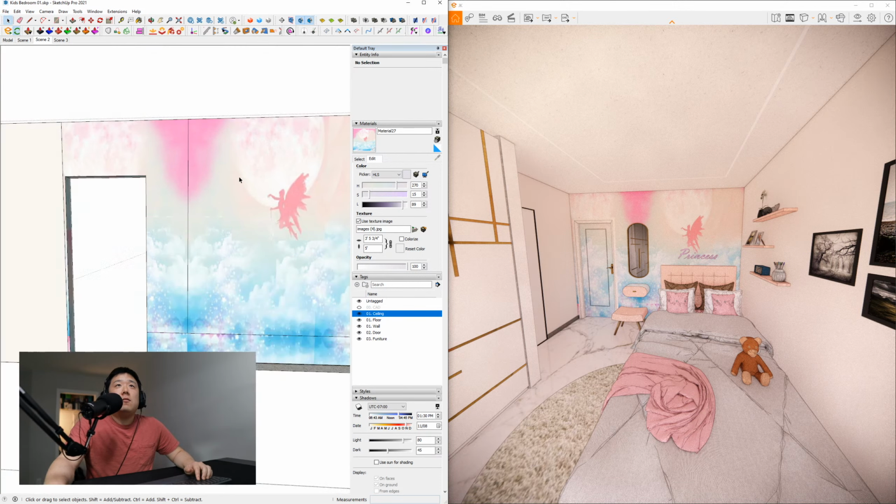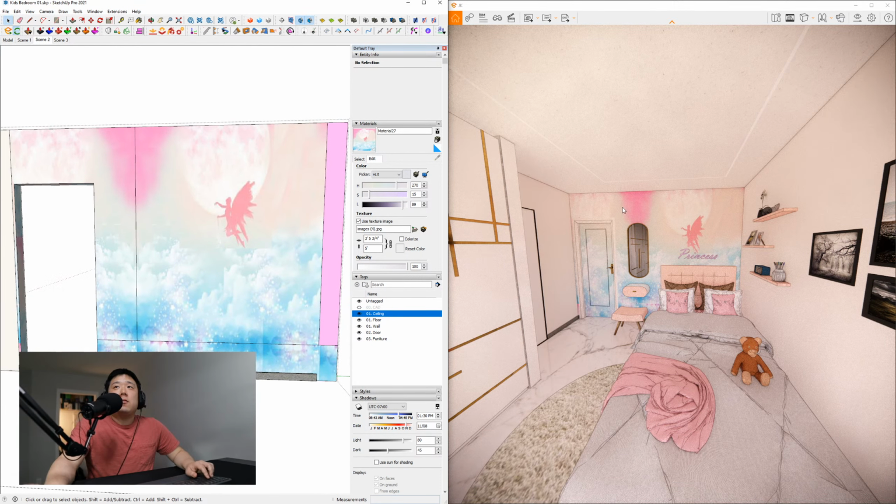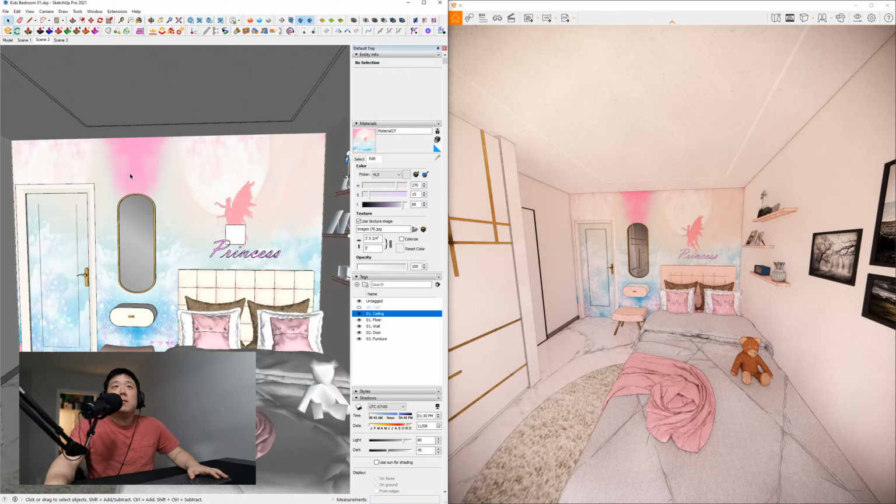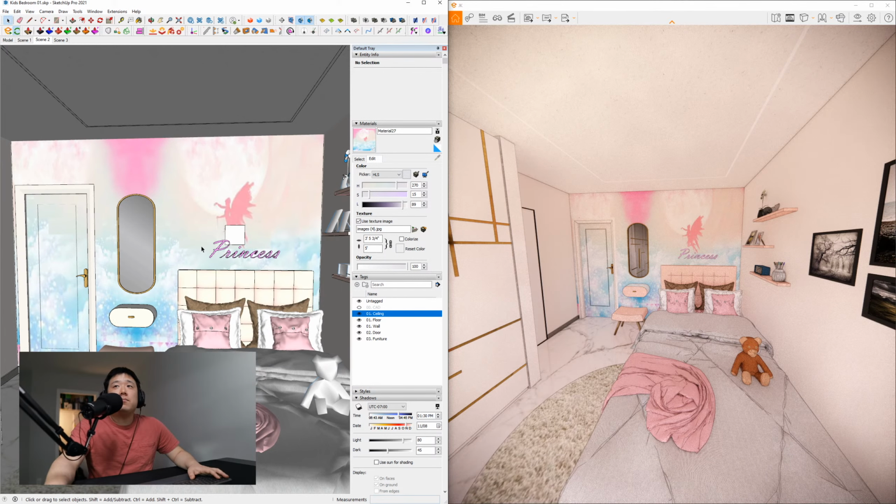So that's what you can do for the sake of SketchUp, although it doesn't really show here. If you want to hide that, hit E for eraser tool or rubber tool for those of you who are across the other side. Hold down Shift key and then just go over these edges, and then it'll basically hide those edges for you so that it doesn't appear as obvious on your scene. So that's what you can do, and that's something that jumped out at me when I was looking at the reference images. So hopefully that is somewhat better.